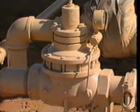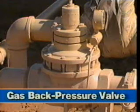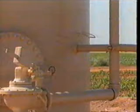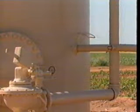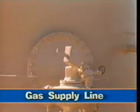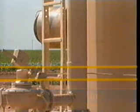Located on the gas outlet line, the gas back pressure valve maintains sufficient pressure to dump the liquids. All sections of the treater operate at the same pressure. To maintain proper operating pressure, some heater treaters have a make-up gas line with a regulator. The gas supply line provides gas pressure to the water and oil dump valves. Now, this line usually runs from the top of the treater down to a drip trap.